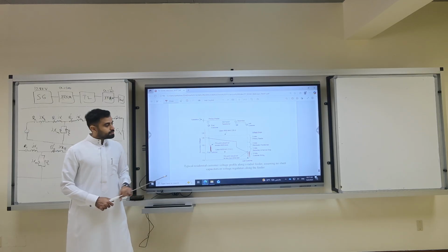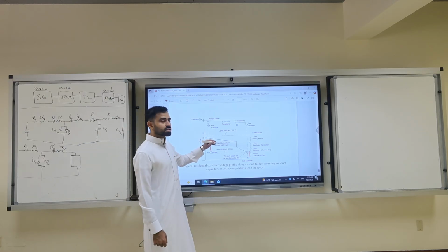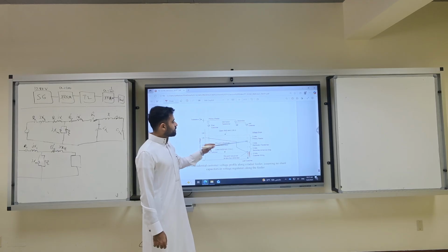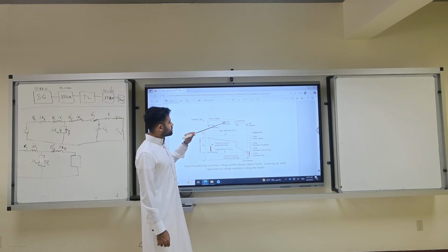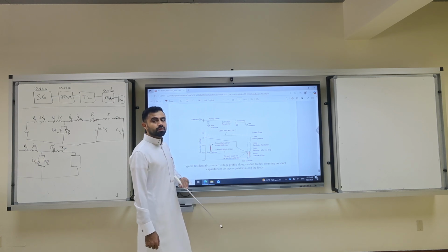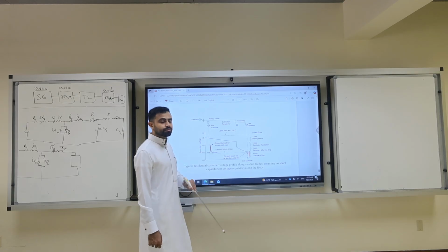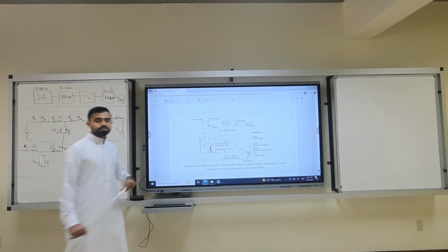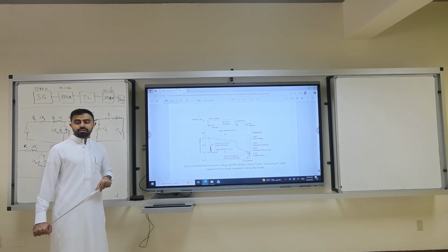No, this is an estimation, not accurate. On the primary feeder across the line you will have a 3 volt drop. The distribution transformer will have 3 volts. Then the secondary and service drop, another piece before every house, will have another 3 volt drop. Then the internal wiring will have 4 volts. Clear?